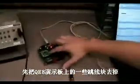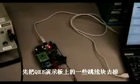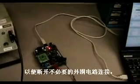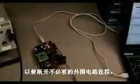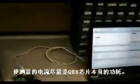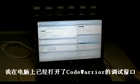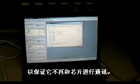So right now I've taken the board, I've actually taken some jumpers off of it, in particular the one that connects to this analog pot, just to make sure that we're getting as low current as we can on this. So I've already programmed my part with the lab. When I've got my computer running, I'm going to go ahead and close the debugger to make sure it's not trying to communicate with the part.